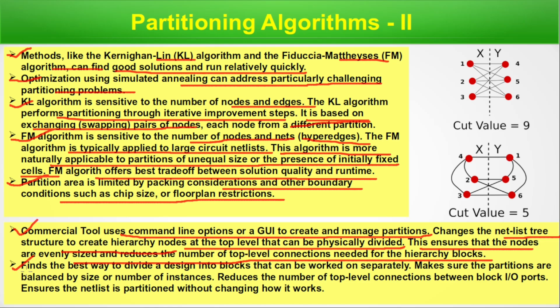They have that algorithm inside them. It finds the best way to divide the design into blocks that can be worked on separately, makes sure the partitions are balanced by size or number of instances, reduces the number of top-level connections between block I/O ports, and ensures the netlist is partitioned without changing how it works.